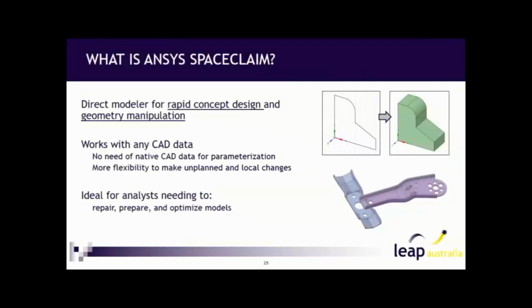On the right-hand side, you can see if you've got something like this, it's something you might want to use shell elements for, so there are tools in there to help you with mid-surfacing. If these things aren't contacting appropriately, you can move the elements around, you can extend surfaces.